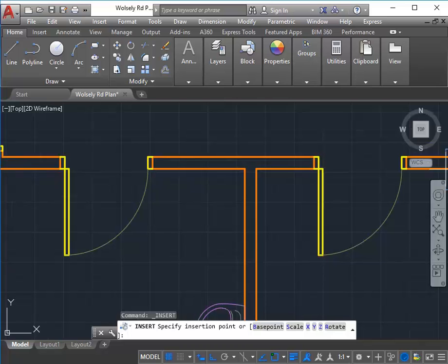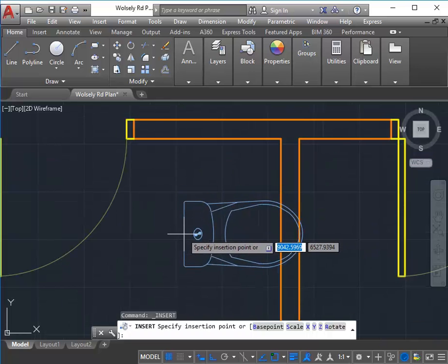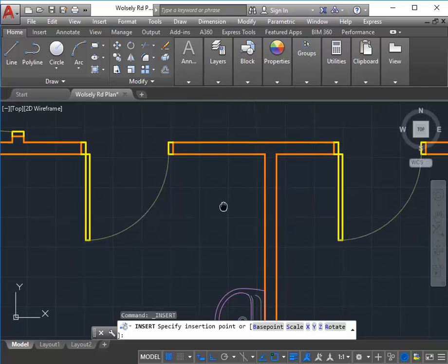But then, have you had a look at some of the good options they've got now for the in-wall systems? How small you can make them? That's the one that I'm talking about. Yeah, that's right, they're fantastic. So have a look at those, and then you'll see that you don't need that huge projection anymore, so that might give you a bit more room in your bathrooms. Oh, yeah, 70 mil. Yep, so you can do them in a 90 mil wall, it's amazing. And so again, I'm going to have my toilet there. This one actually does have a system, but even if you want one that doesn't, you can put it up against your wall.